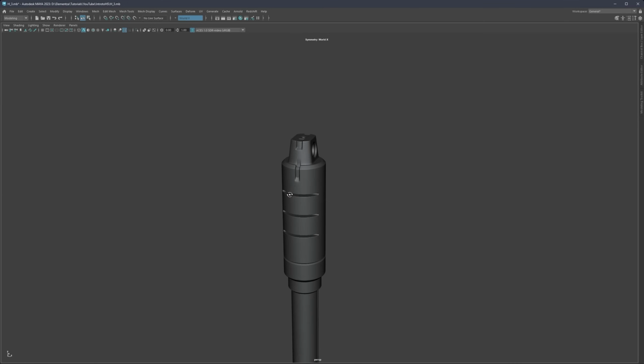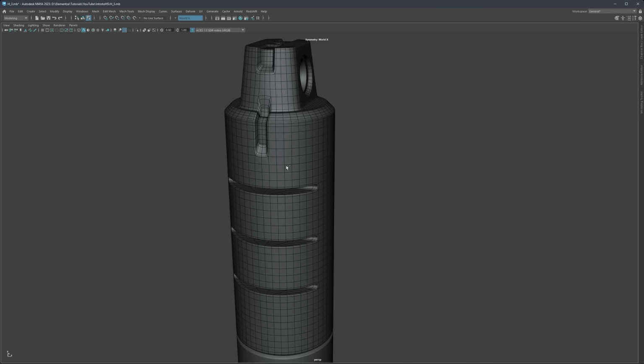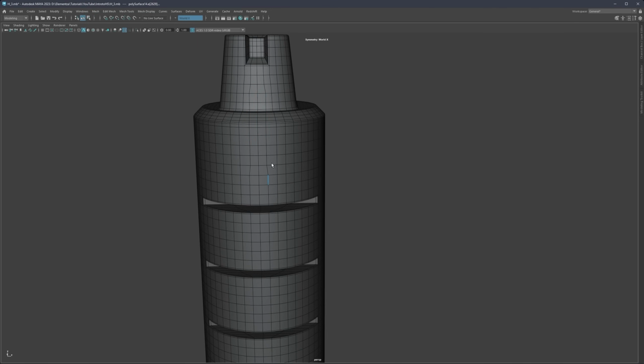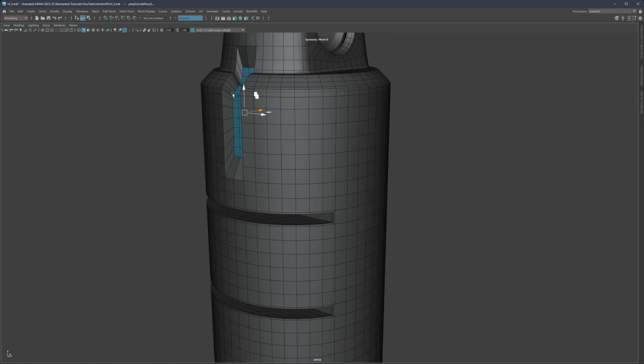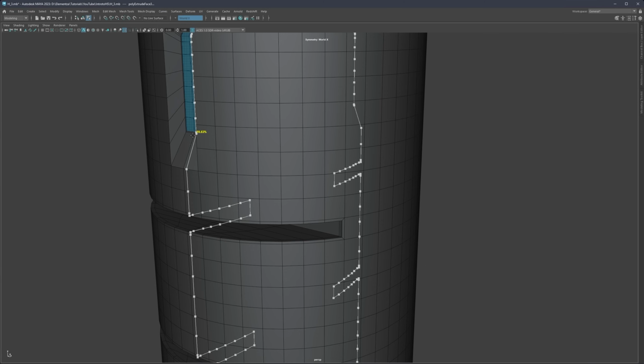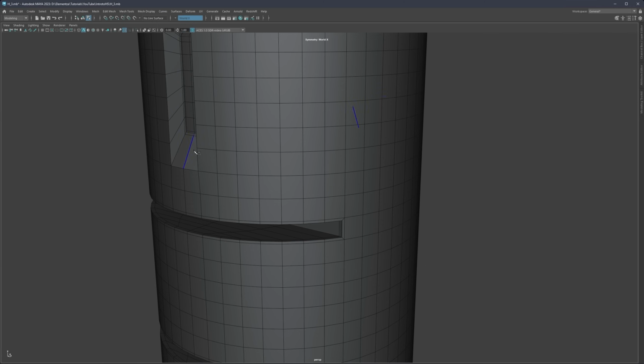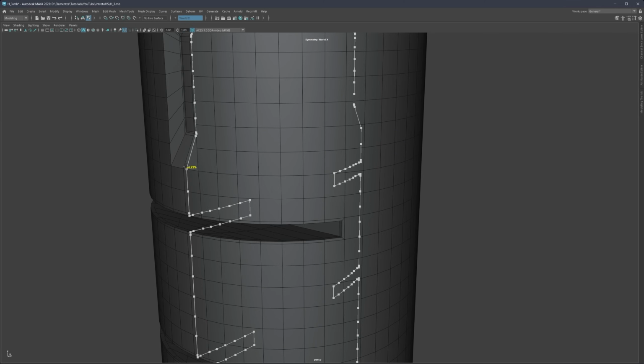And the thing is, yeah, maybe I would like to have it even more down. So let me undo this and I'll just quickly repeat all of this. So just slide this and same thing. So just quick scale, quick push on the inside, small offset with the extrude, and with the multi-cut, 2 cuts here.